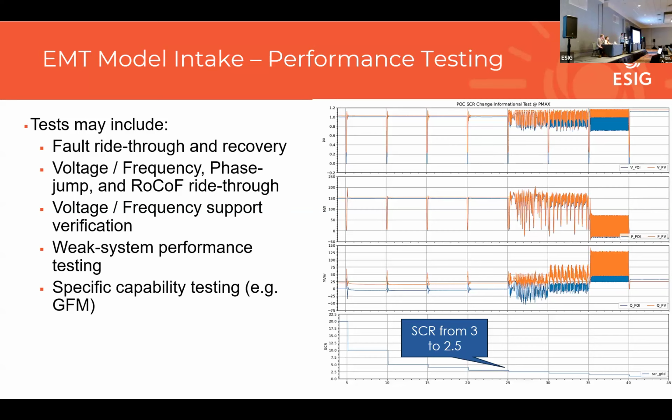They're doing hundreds of tests in these simplified test systems. You can test across the full reactive power capability range. You can test across the full active power range of the device. You can test all kinds of different system strength and different voltage and frequency profiles. So it's a very sandbox environment for you to play with the model and probe it and make sure that it meets your needs.